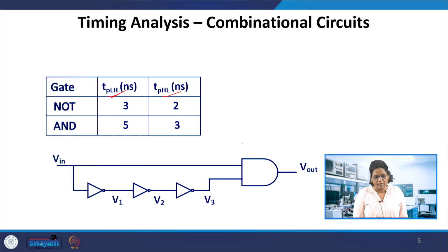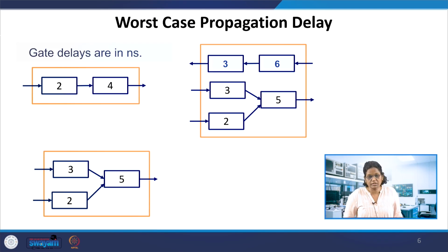So far we have seen combinational circuits which don't include any propagation delays. Maybe in Verilog code, when we do the synthesis, we can see the technology-specific propagation delays for each of them. Apart from that, we can also specify a particular delay for the gates when we develop Verilog modules.